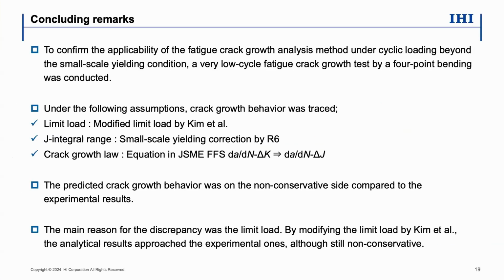So, concluding remarks. As a first step of the study to confirm the applicability of the fatigue crack growth analysis method under cyclic loading beyond small scale yielding conditions, a very low cycle fatigue crack growth test by 4-point bending was conducted.